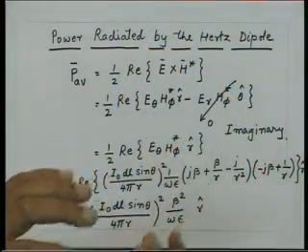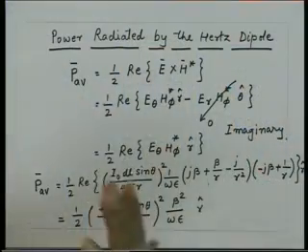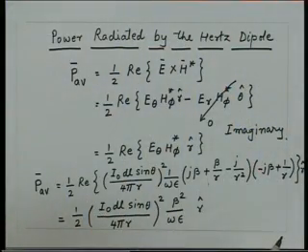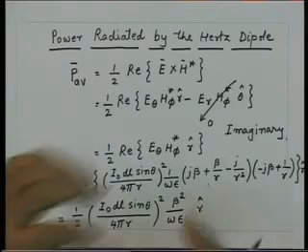So, the power essentially is going to flow radially outwards, it is in direction r, and it is solely going to be because of the radiation fields. So, other fields which are electrostatic field and the induction field, they essentially give you the reactive fields, whereas the radiation field essentially contributes to the power flow because it takes away the power from the Hertz dipole.